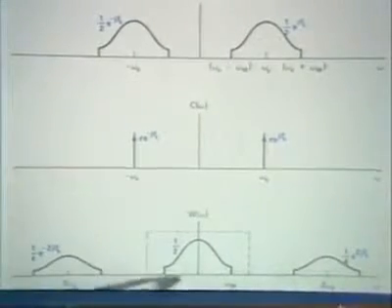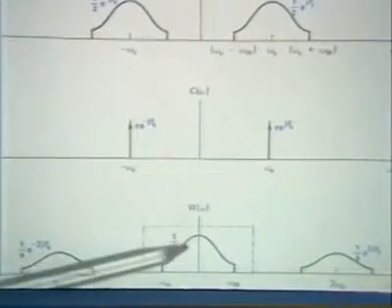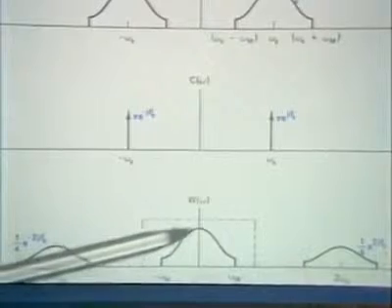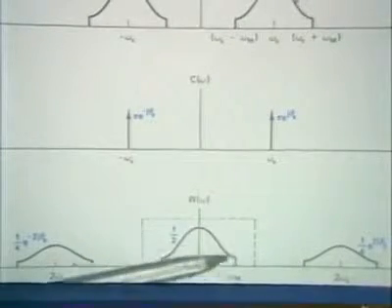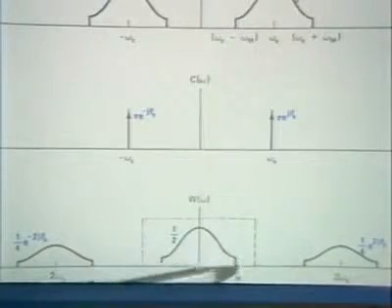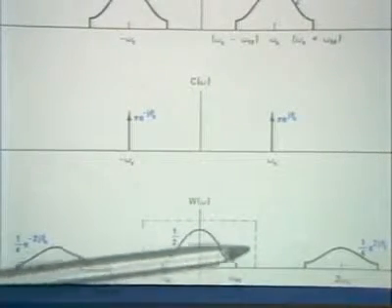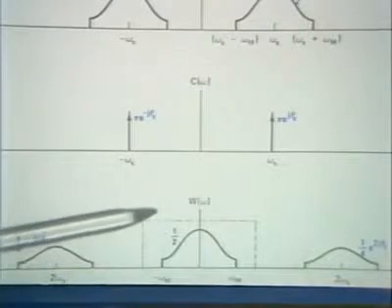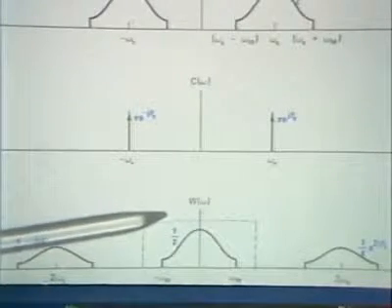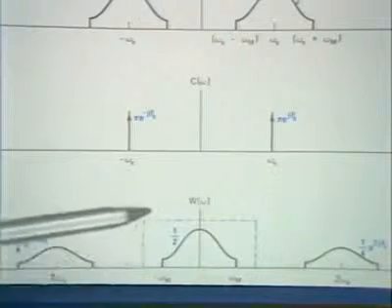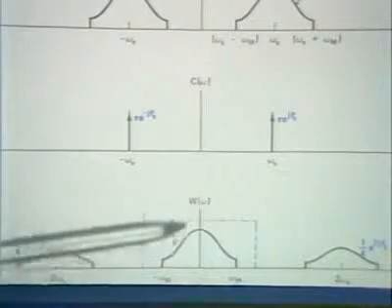And let me just draw your attention to the fact that, because of the way the algebra works out, the amplitude of this replication of the spectrum is half what the original spectrum was, and that means that ideally, to keep scale factors correct, we would choose the amplitude of this to be 2, to scale this back up to 1.